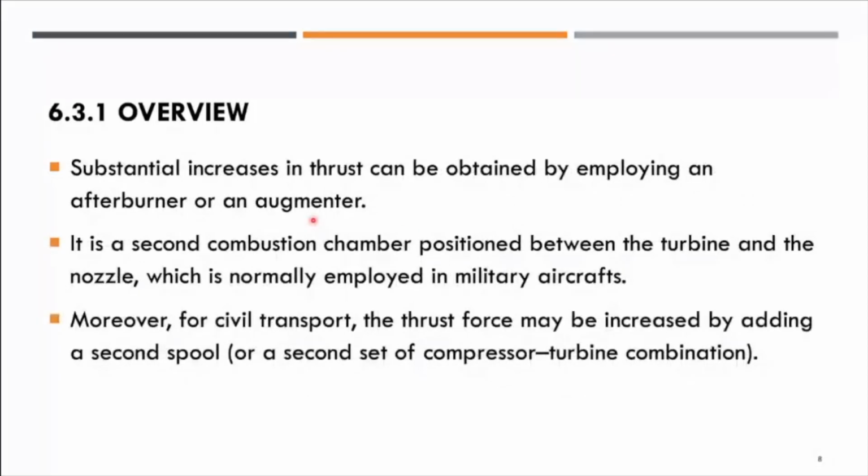Substantial increases in the thrust can be obtained by employing an afterburner or an augmenter, where the hot exhaust from the turbine will be burned again.